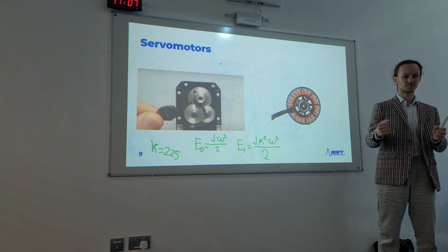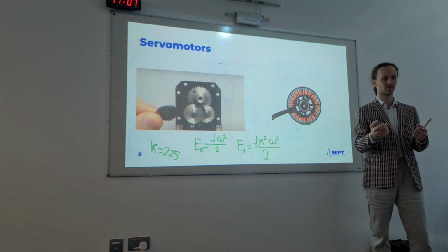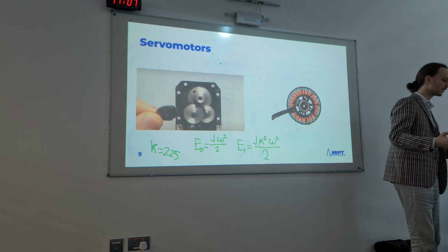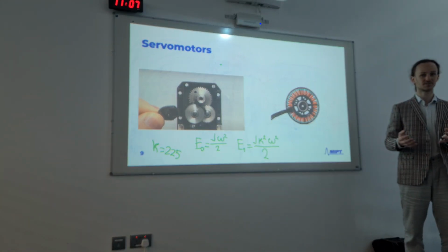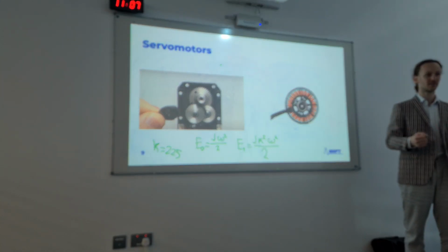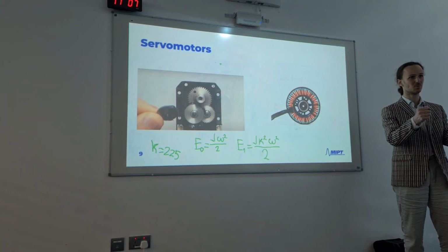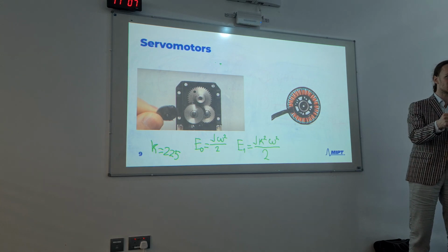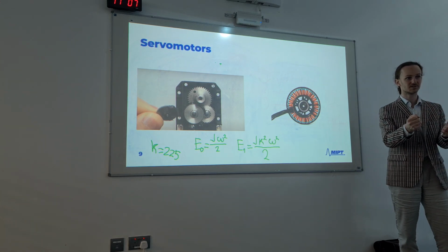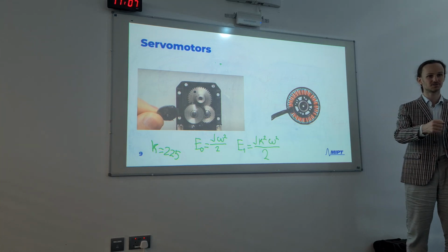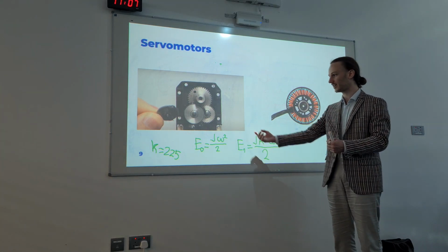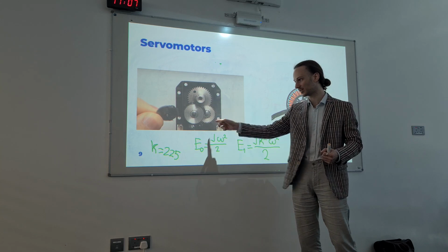You will have to move around the limbs of the robot. You will understand the internal inertia of this rotor. It will be really evident. If you just slowly move the limbs of the robot, you will feel that it is kind of acting against the change of the angular velocity because of this very high inertia that is hidden inside of the servo motor.